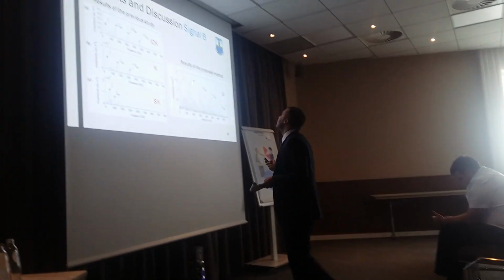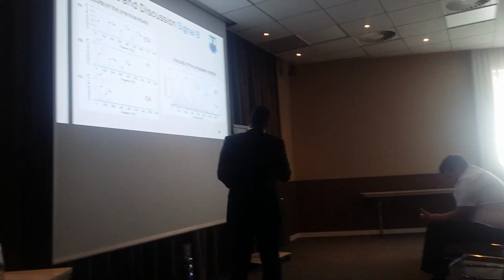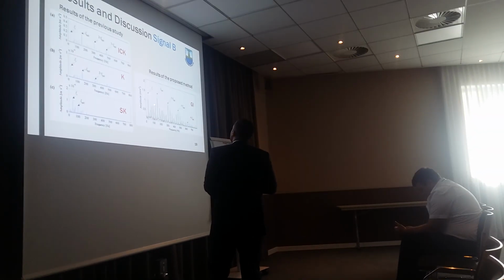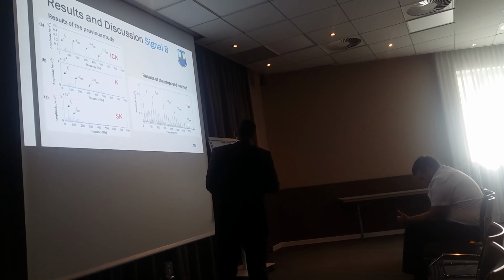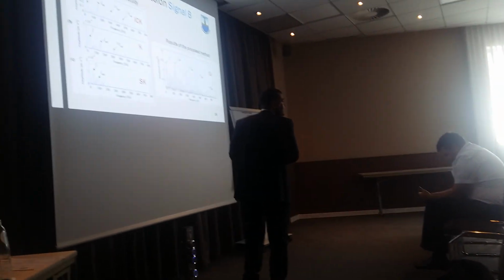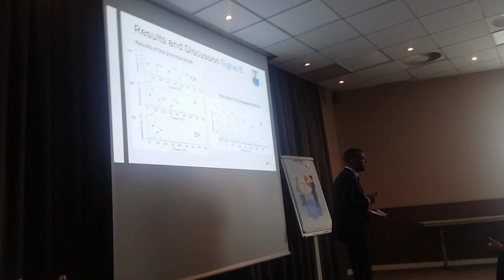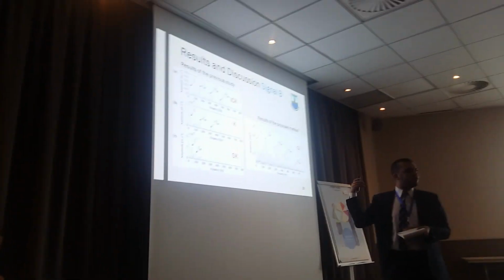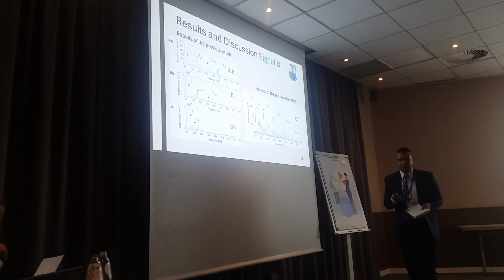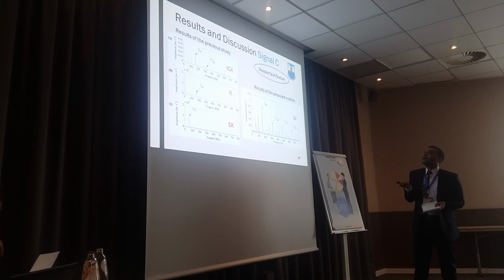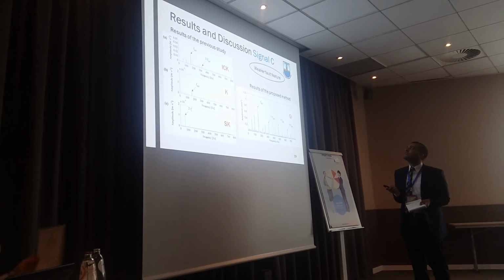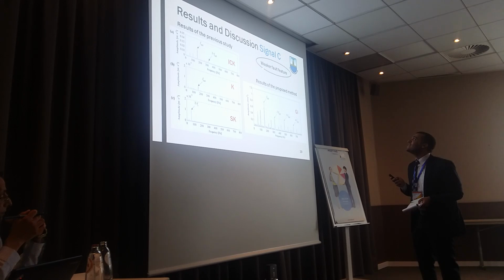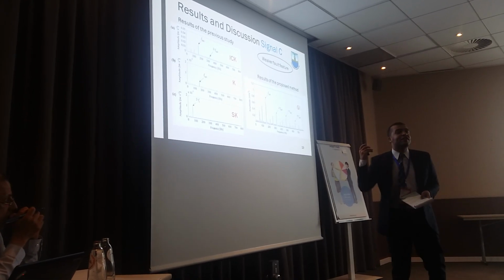Whereas the results based on my filter, which is based on Gini index, revealed up to the fourth harmonic of the bearing characteristic frequency. Which proves that Gini index is more powerful than the previously used criteria. Now the results of processing signal C, which has a weaker fault feature according to its conditions.